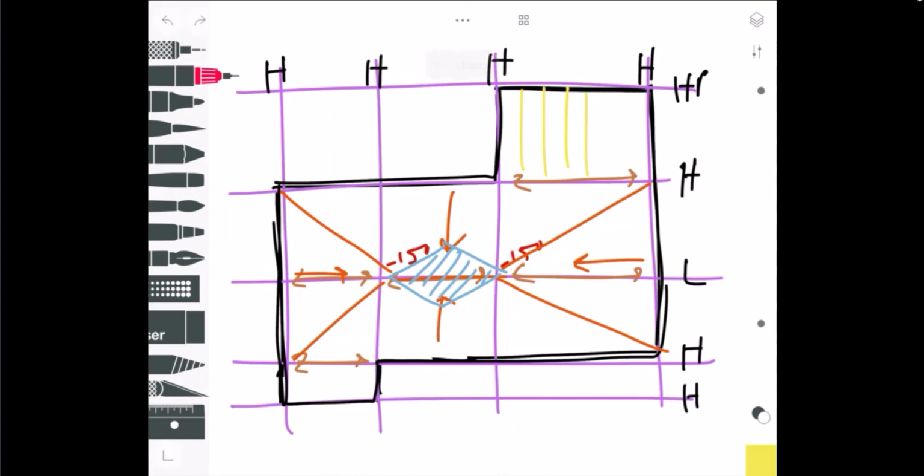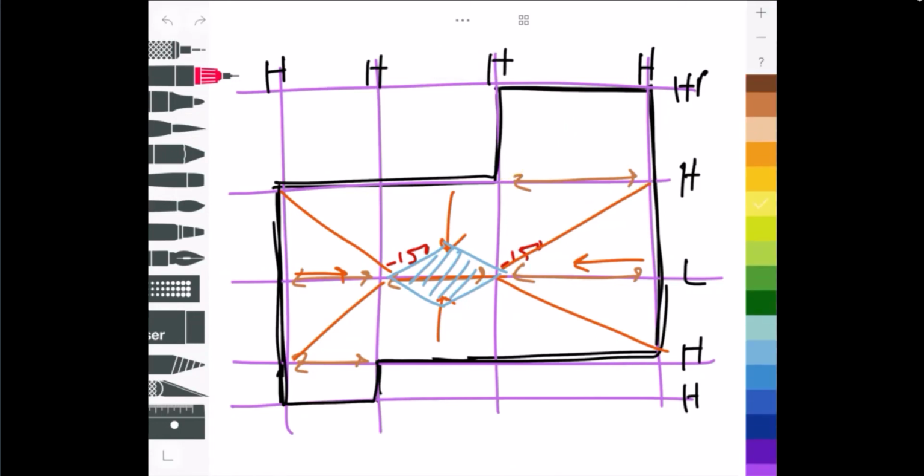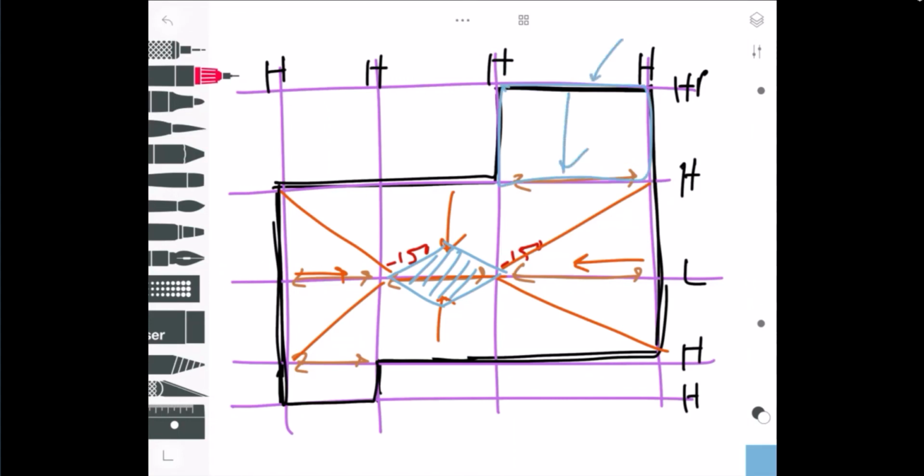So what would I do in this case? This beam here is flat, so I would probably do a sloped insulation package for this whole portion right here. I'd slope it down and make sure my parapets were high enough to deal with that sloped insulation. The same would happen down here as well. So that's the approach to take a stab at laying out structure in your building.